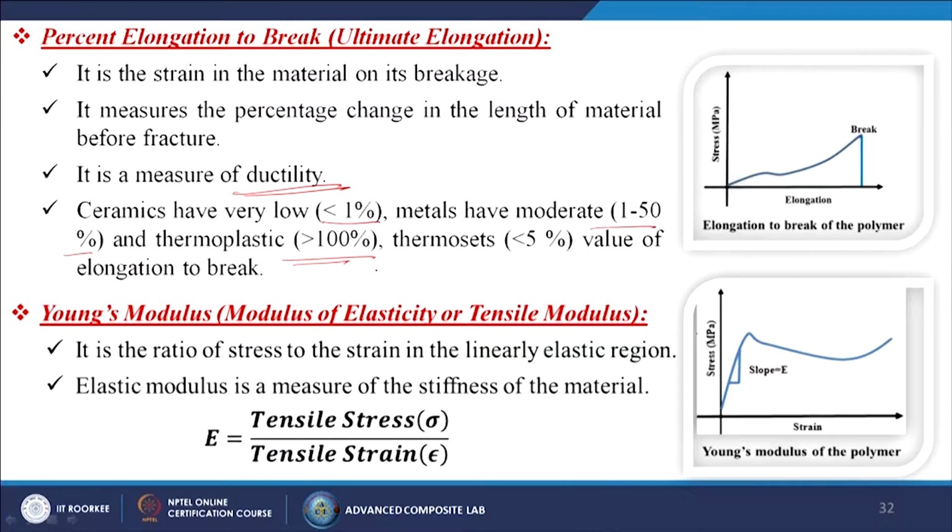What is the Young modulus, or maybe the modulus of elasticity, or maybe the tensile modulus? It is the ratio of stress to the strain in the linearly elastic region. Elastic modulus is a measure of the stiffness of the material. So, generally it is denoted by capital E, which is nothing but the tensile stress sigma divided by the tensile strain,